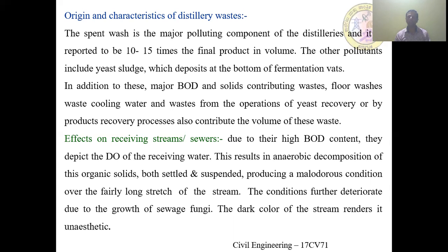When DO is depleted, there is decomposition of these organic solids, both settled and suspended, producing malodorous conditions over a fairly long stretch of the stream because of the high volume of BOD. So it creates a nuisance. Anaerobic condition means a septic condition.